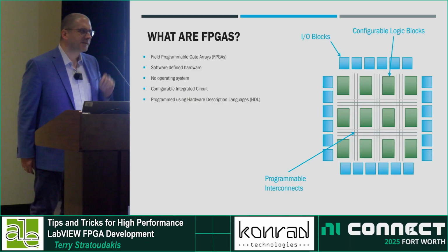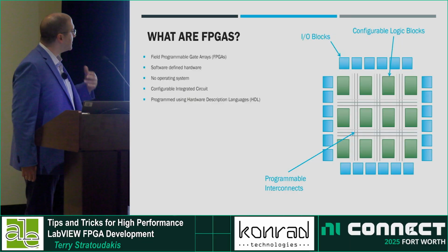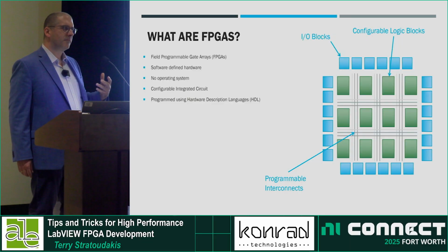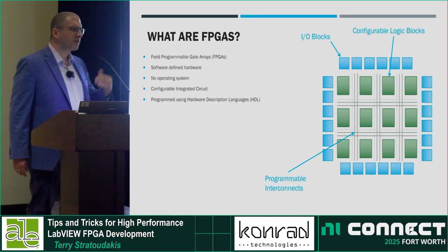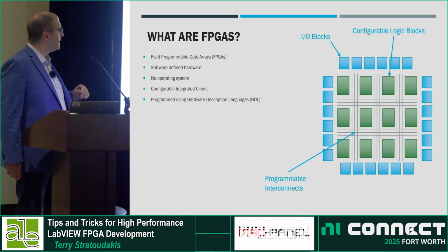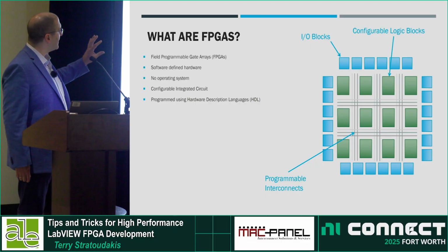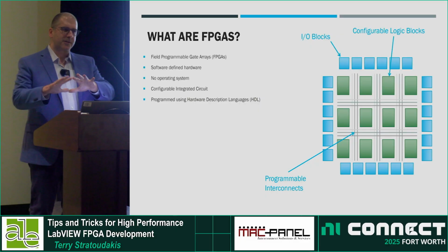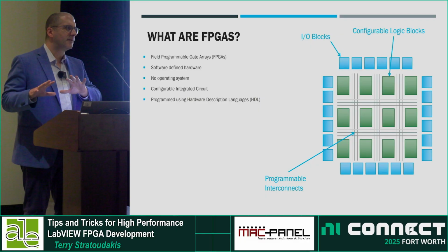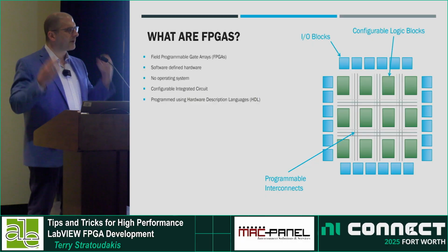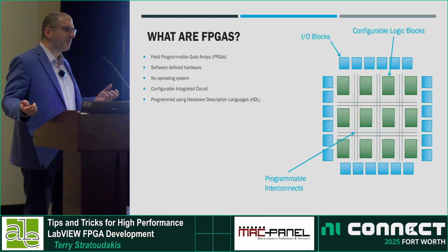Another thing that's important to understand about FPGAs is the spatial aspect of them. And certainly LabVIEW FPGA abstracts that for us. But it is important, again, when you're doing more of a high-performance system, to understand that there is something spatial. Things will have to get placed and routed at some point. It is important to understand that, especially if you get a compile failure.